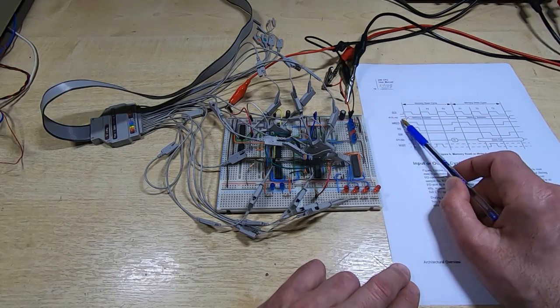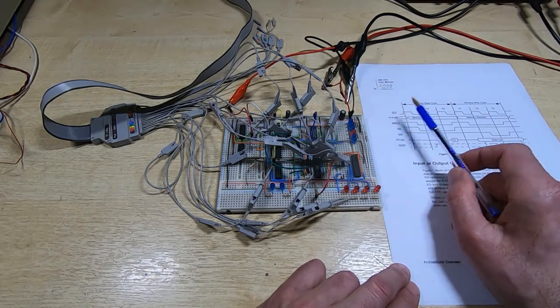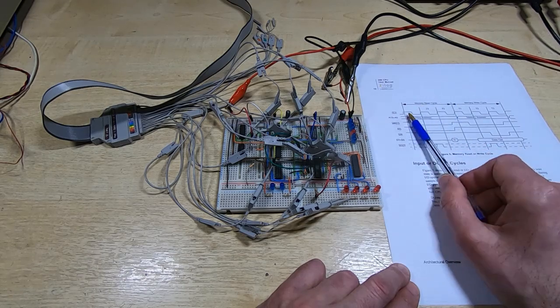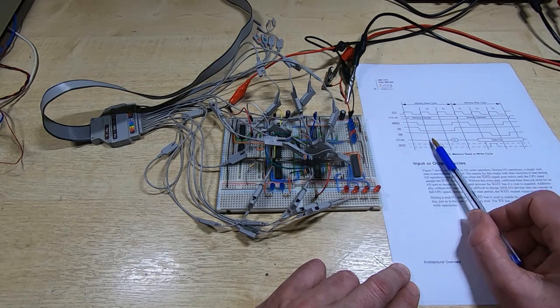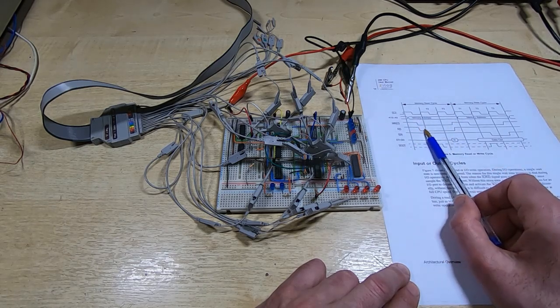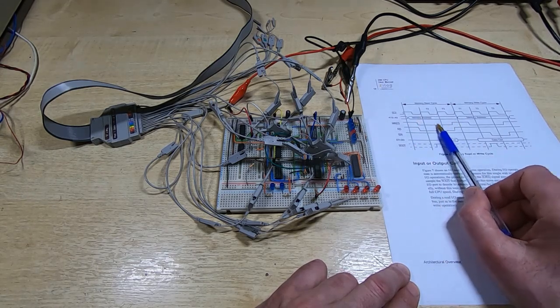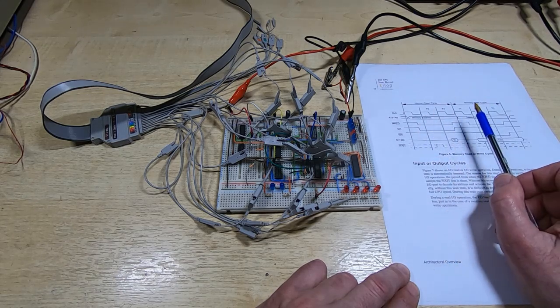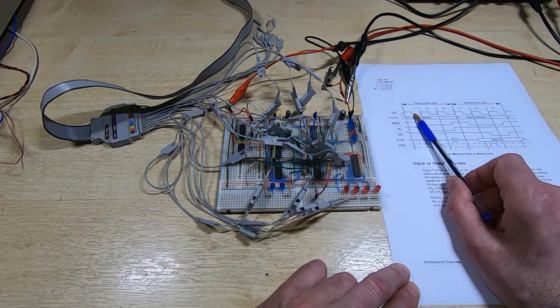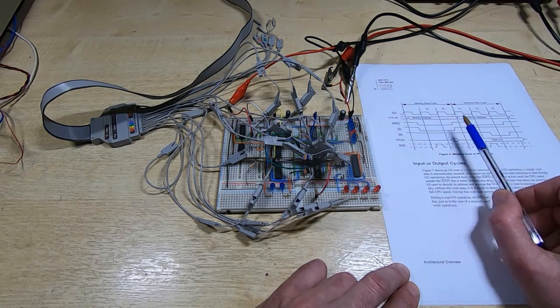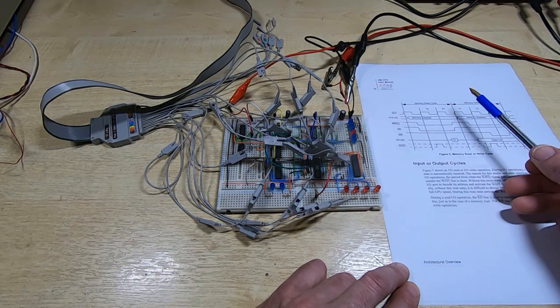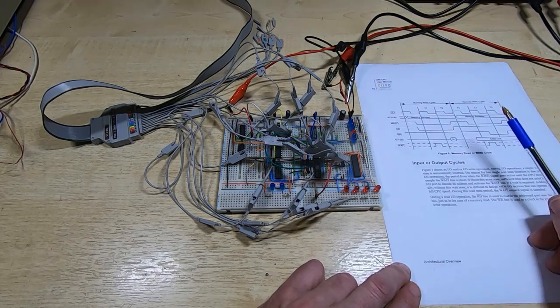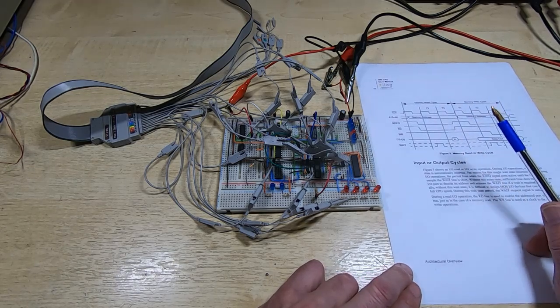We don't need to simulate or emulate that because we're not going to be fetching instructions, but we do need to provide this sequence of clock cycles and signals in this sequence and with this exact timing. So we need 3 full clock cycles, and then we will need at least another half clock cycle to end the process and hand control back to the Z80.